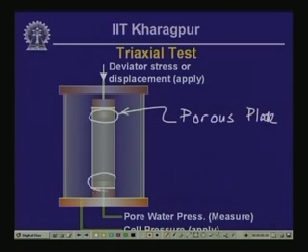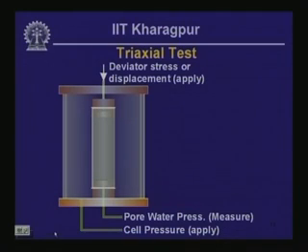And similarly, there is another porous plate at the bottom, and that allows us to measure the pore water pressure within the element, and we are going to explain what is meant by that when we go further on soil and rock testing in one of the later presentations. So, this is how we actually conduct a triaxial test.